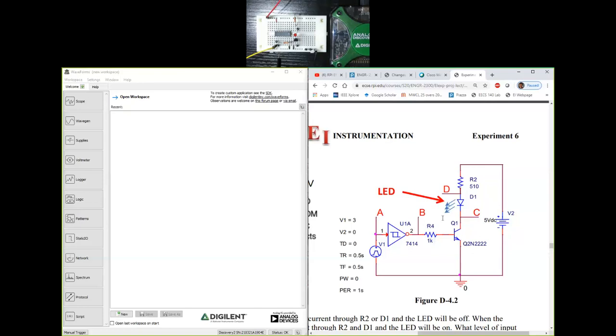So we'll begin with the one that you see on your screen. So it's a voltage source connected to 7414, 1 kilo ohm resistor, to the base of Q1. So let's start here. V1 is a voltage source, and I'm going to use the yellow wire from the analog discovery to provide that particular voltage waveform. So let's try to set that up in my waveforms window.